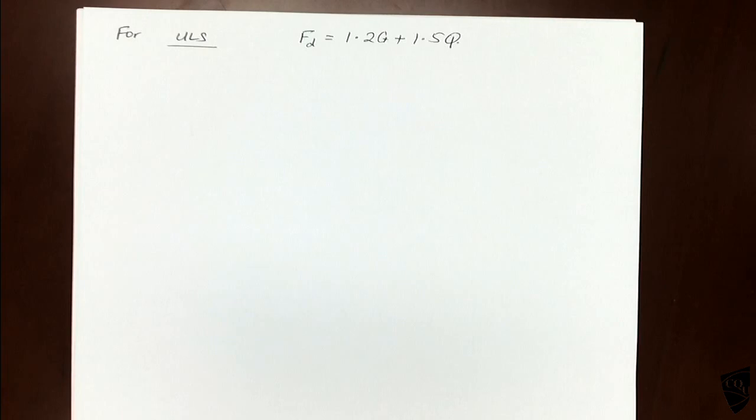Okay, so you just make sure when you submit the design, assignment 1, use the correct load combination. For serviceability, we have to use the serviceability limit state load combination. If you look at the tutorial workings, we use G plus Q, or G plus short-term Q, or G plus long-term Q, something like that. Okay, so here the worst case is 1.2 G plus 1.5 Q.